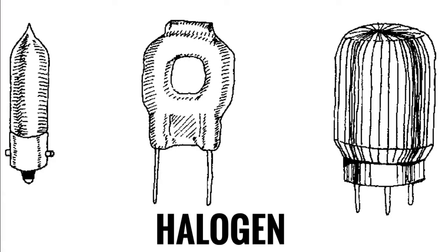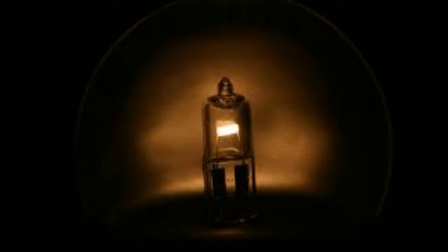Second type is the halogen lamp, which is basically similar to incandescent lamp or an offspring of incandescent lamp. This lamp has high power and provides ultra bright light. The filament inside is coated with quartz and filled with halogen gas like bromine or iodine.